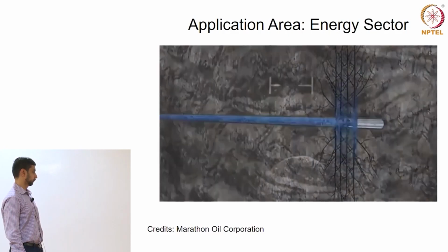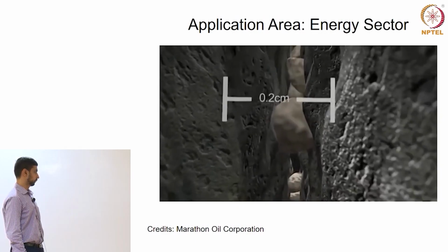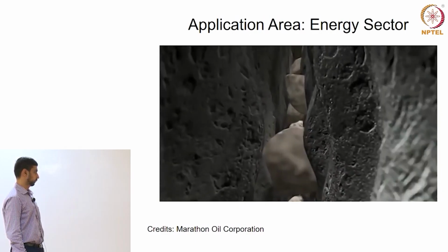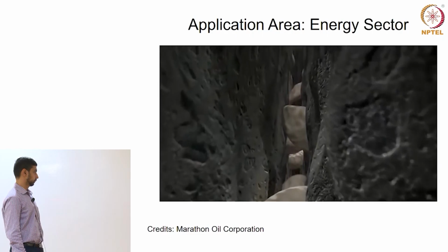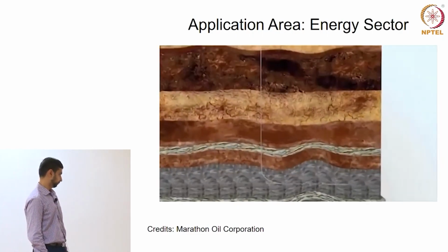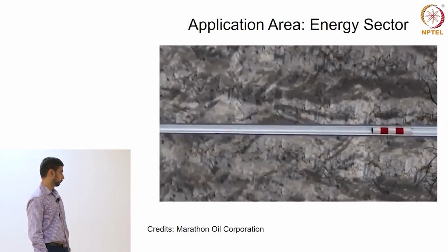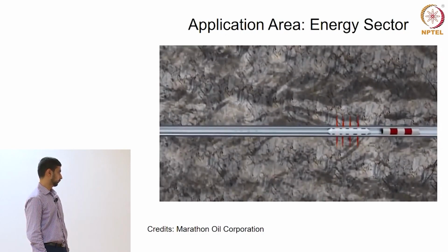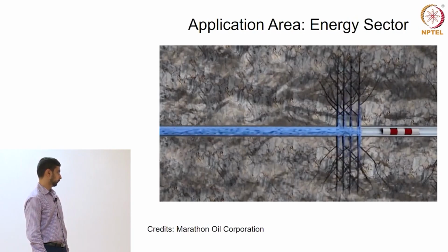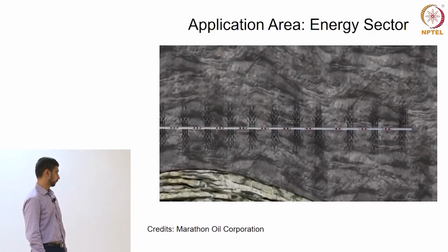The sand in the frac fluid remains in these fractures in the rock and keeps them open when the pump pressure is relieved. This allows the previously trapped oil or natural gas to flow to the wellbore more easily. This initial stimulation segment is then isolated with a specially designed plug, and the perforating guns are used to perforate the next stage. This stage is then hydraulically fractured in the same manner. This process is repeated along the entire horizontal section of the well, which can extend several miles.